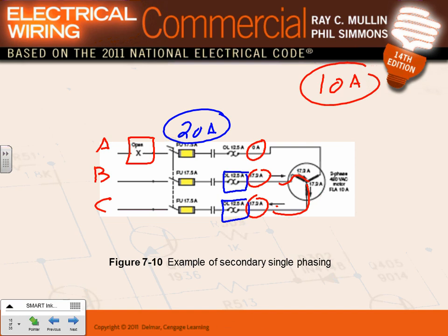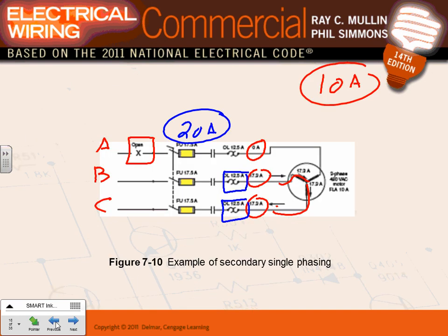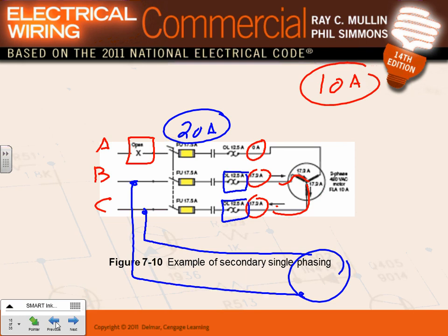Okay, single phasing. Now another thing, guys, that could happen for single phasing. If you have another machine, this is really interesting. If you have another motor here, and this motor is all connected from two phases. Suppose this is a 10 amp and this is a 2 amp motor, right? If you single phase, here's what happened. And this is also another three phase coming to it, three phase.